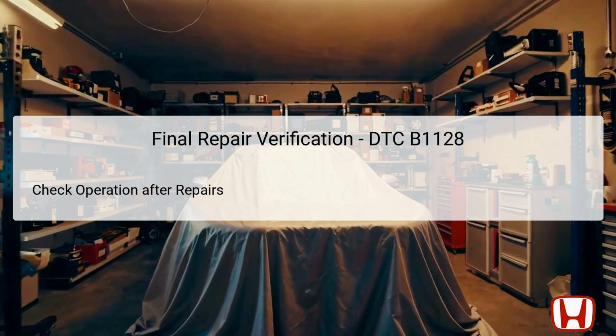After conducting these tests, it's wise to run a final check using the Honda Diagnostic System, HDS, to ensure no new trouble codes have emerged. Effective verification solidifies that the issue has been resolved fully. If faults reappear, further diagnostics may be necessary, returning to prior steps to reassess the circuit and components involved.